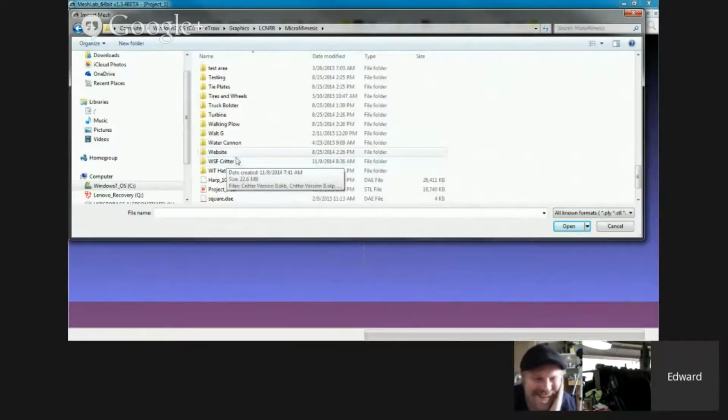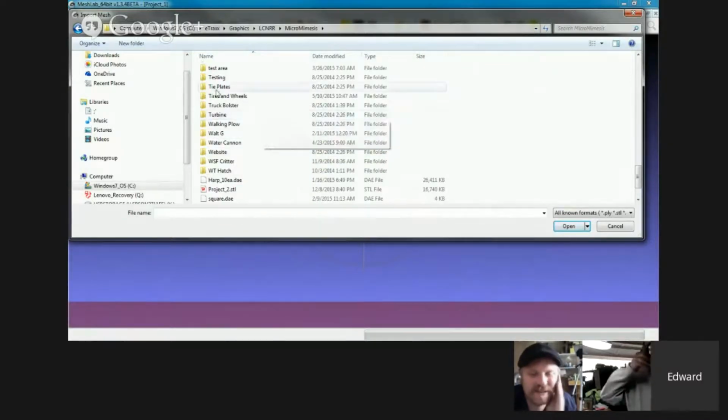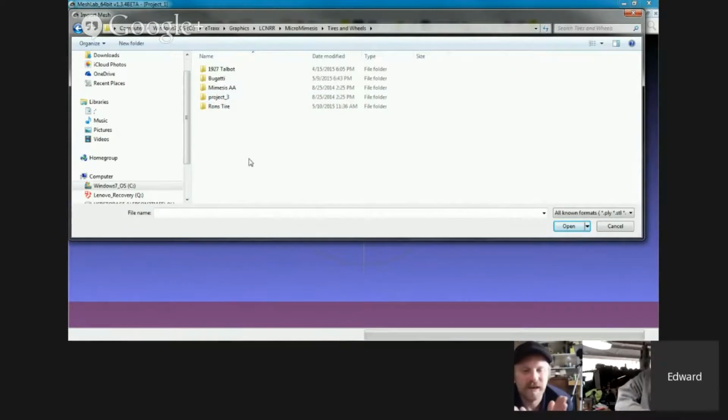And there's a way to make a regular tread. Basically, what you do is you make your tire without a tread, and basically you make like a pizza pie cut on it. You create the tread on that piece, and then you spin that pizza pie around to multiply your tread. Instead of having a flat profile, you're saying make one section with a section of tread in there to copy around your circle or follow around your circle.